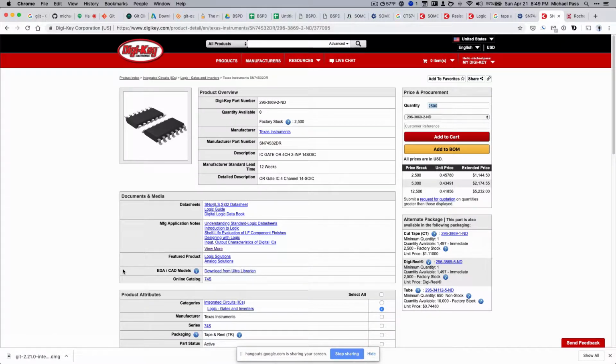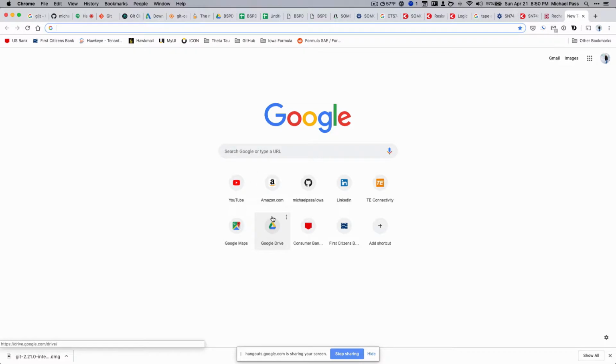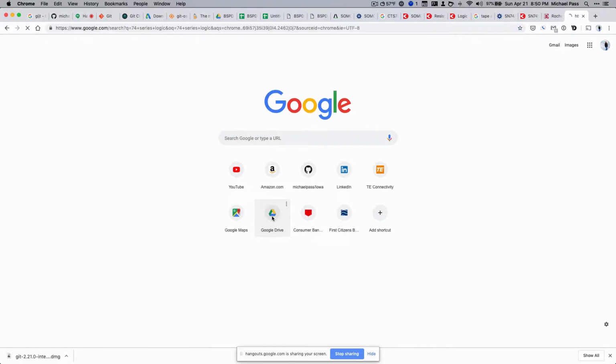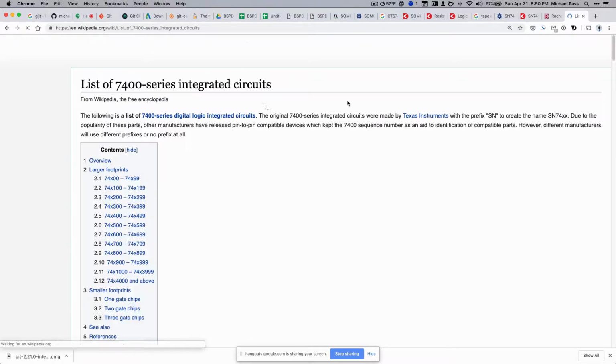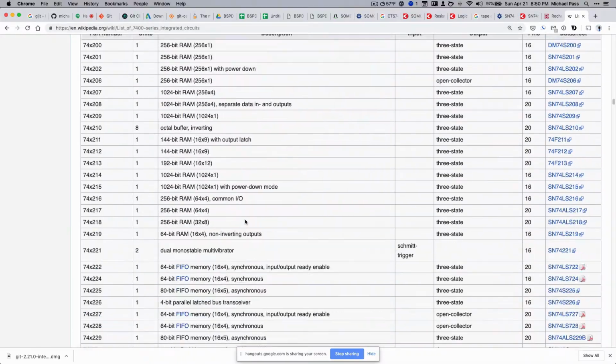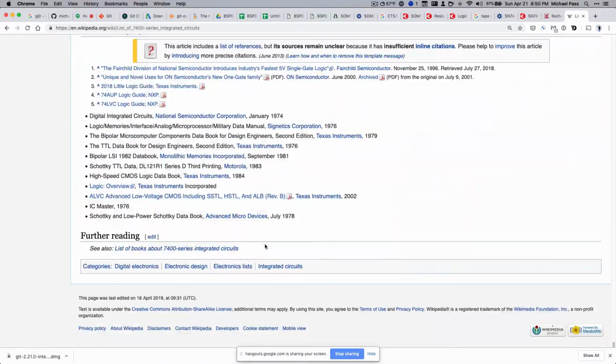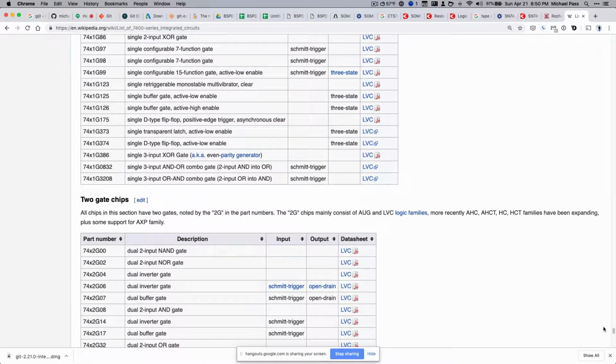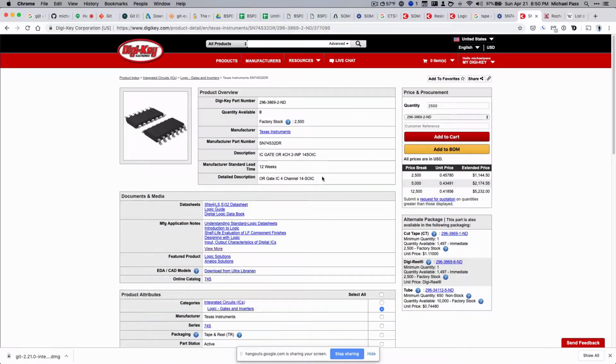Wait, what did you search? This might actually be hard for other people to do. I looked up 74S. S is just Schottky diodes. As far as what the difference is here, logic families, let's see. Anyway, because you knew the logic of the circuits, you were able to get a cheaper part, since you knew a similar chip would also work. Yeah. At least with me and Zach, because we don't have that extensive knowledge, I don't know if we'll be able to figure that out.